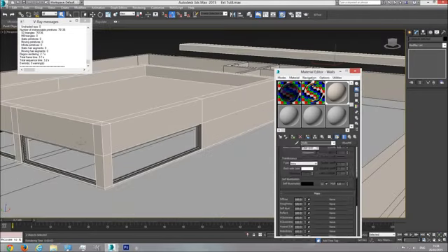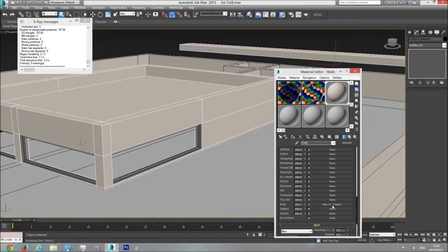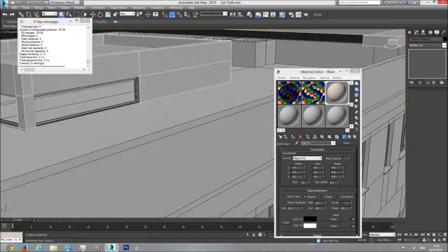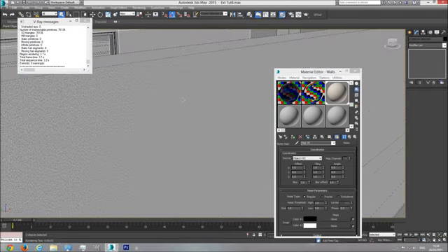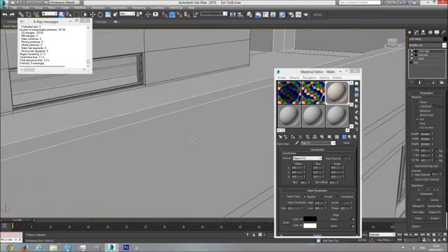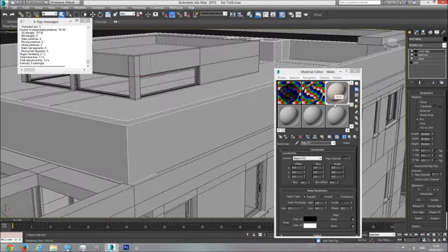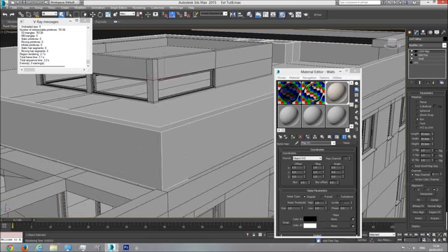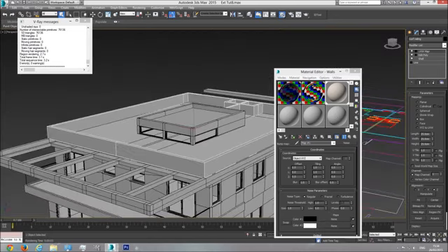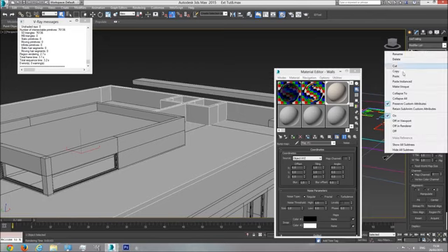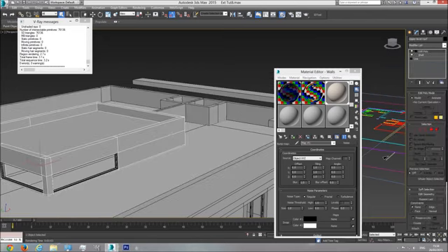If I go to the bump map, hit on it and click on show shaded material in viewport. So now I can see the bump map. It is aligned correctly because I'm using the UVW map modifier on it. So it aligns the map of the bump map correctly on an object. What I'm going to do is copy this UVW map over to here.